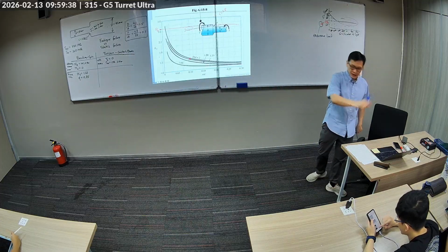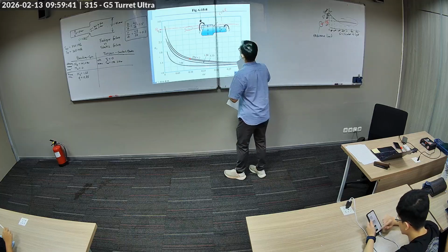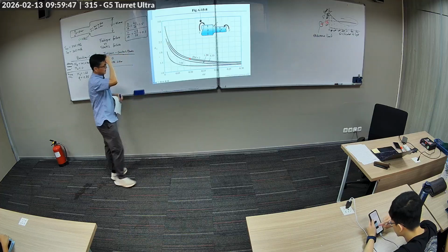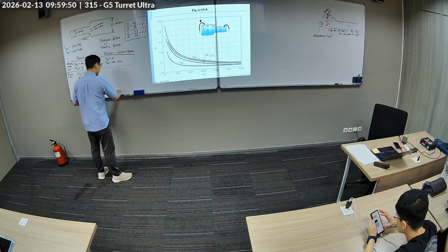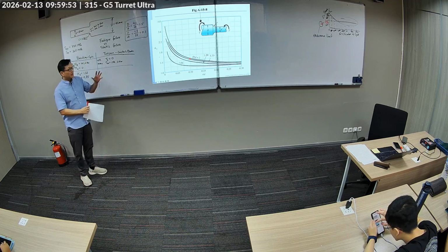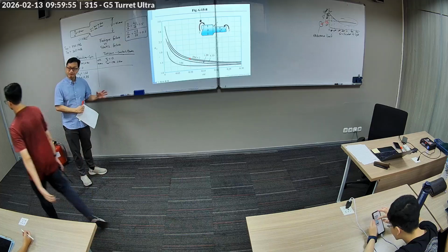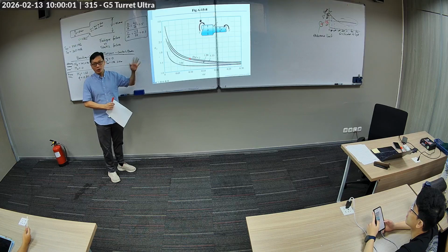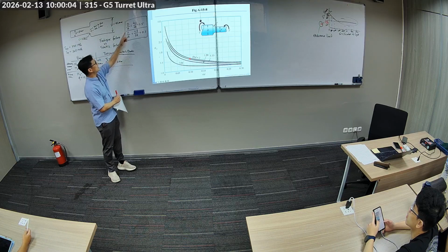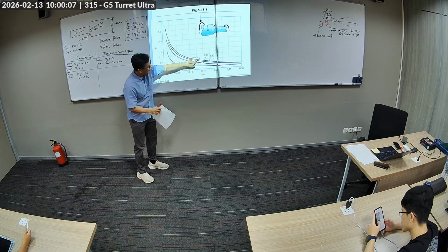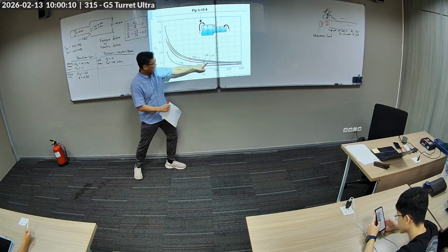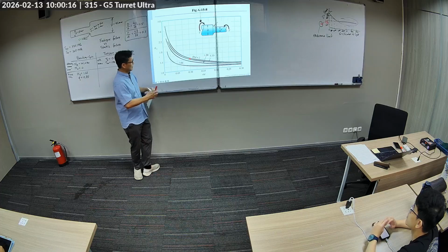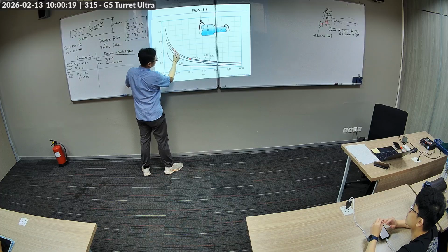Not done. Torsion. So this is the torsion chart for KT. Same usage. Now you tell me, what's the first step? In using this chart, what's the first step? Pick the line based on not r over d, D over d. Big D over small d, 1.5. I have this line D over d equals 2. This line D over d equals 1.33. So yeah, somewhere in between those two lines, right? Let's draw our magic art.